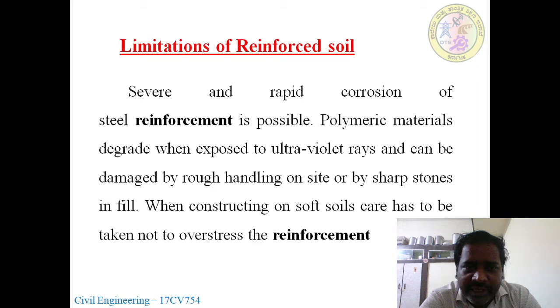Polymeric material degrades when exposed to ultraviolet rays. So we have to take care about the degradation. We have already studied this in the disadvantages, and it can be damaged by rough handling on site, or by sharp stones in the fill. So we have to take care about the small stones in the soil.